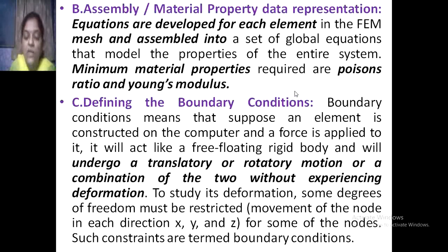To study its deformation, some degrees of freedom must be restricted. So the movement of the node in each direction, that is x, y and z, for some of the nodes, such constraints are termed boundary conditions.